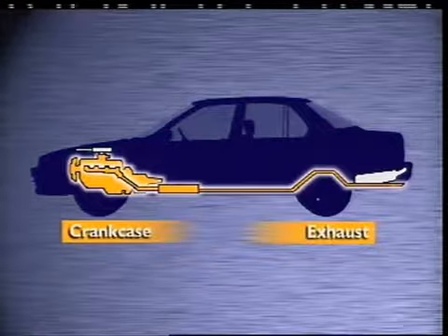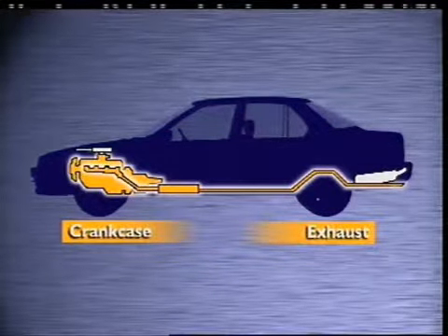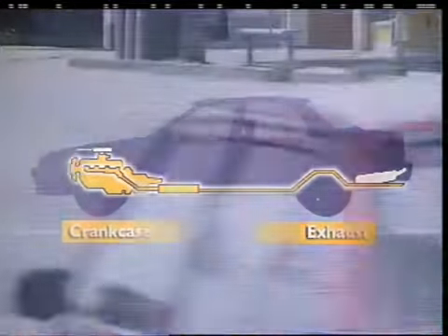The crankcase and exhaust system emit pollutants directly from the engine into the atmosphere. They are caused when hydrocarbons, lead compounds, and oxygen and nitrogen from the air are burned in the combustion chamber. In a compression ignition engine, emissions originate from the engine and escape to the atmosphere from the exhaust and the crankcase breather.